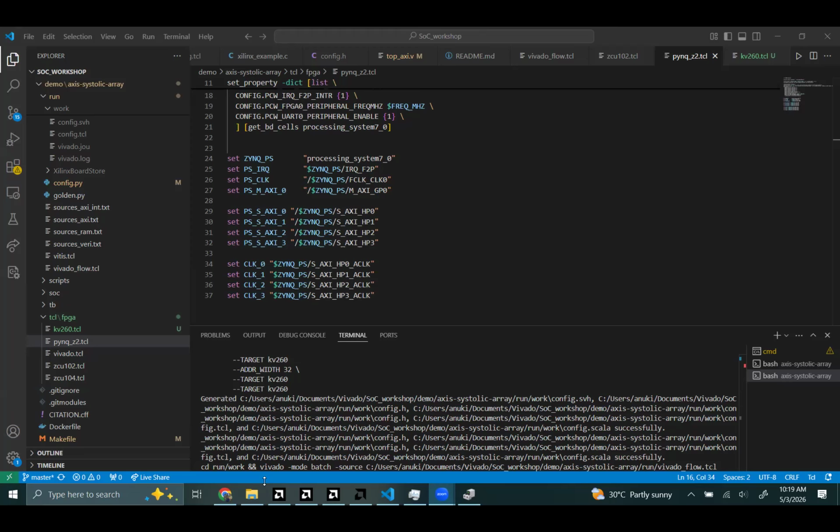We had this problem right now: the thing that was running previously was hanging when you build things through the GUI. It can take several hours to debug why that happened. Usually it might be some port width mismatch, or whatever the issue was. So you have all these problems. Then I highly recommend you keep as much stuff as you can in Verilog, right? That means use open source IPs and put everything in Verilog.